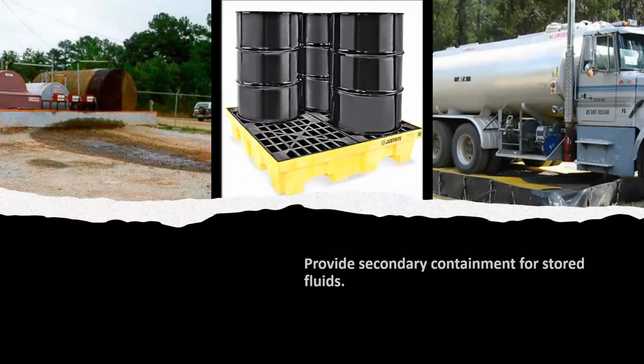You also want to provide secondary containment for any stored fluids. This is required as a part of the SPCC plan. So if you have any type of oil on site and you're covered by the SPCC plan, you have to have secondary containment. And that's something that we see missing at a lot of sites. So there's some options here.